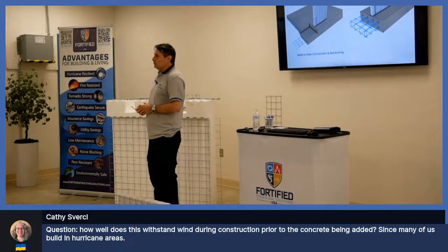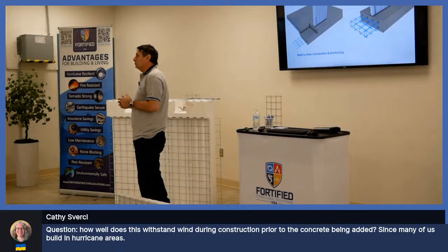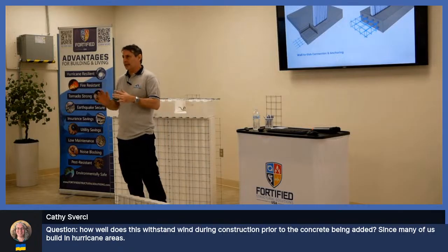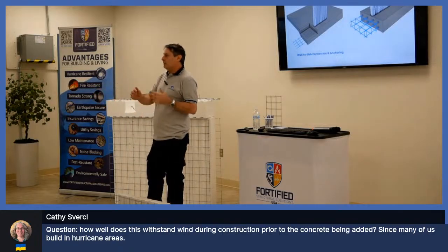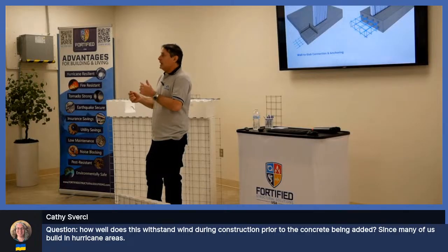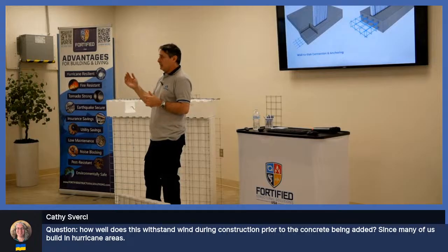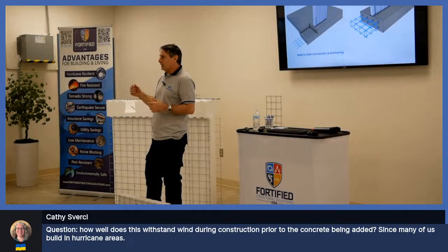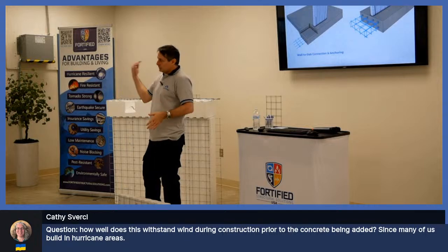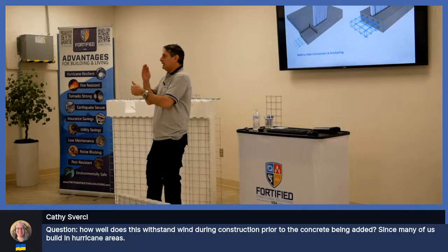And one thing that I always suggest, and this has to be clear: if you have a project of 2 stories, you never ever place the second story if you haven't sprayed the mortar on the first one. It's better to spray the mortar on all the outside first, and then try to have some interiors.